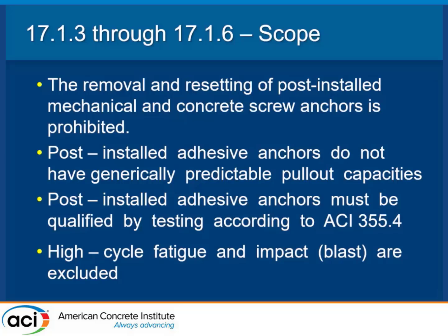All right, we have a beautiful picture when we're trying to explain the certified installers. Like when you put the epoxy in the hole, they had this camera on a group of workers, and they were trying to do such a good job. They filled the hole with epoxy, and they put the anchor in, and they took it out to make sure it was all covered, and they shoved it back in again. And meanwhile, all this epoxy is just going everywhere, and it's just like, no. So in general, you can't install it, uninstall it, and put it back in again.